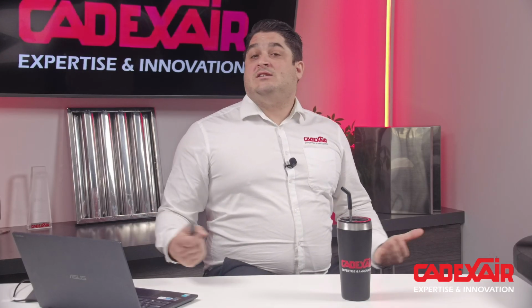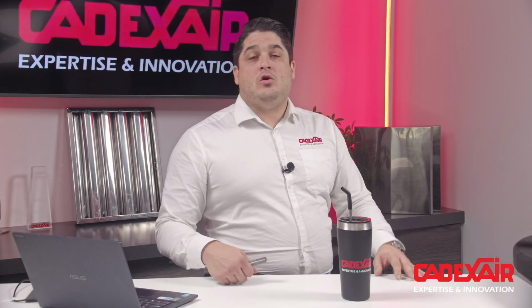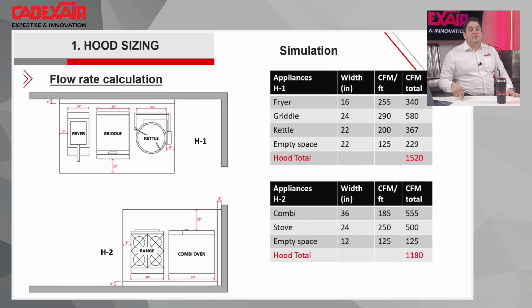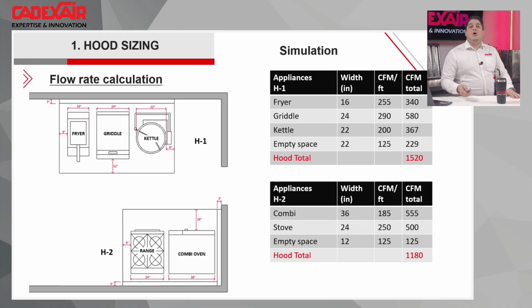How it really happens at Cadexair is, when we are creating the system for each hood, we have drop-down lists with equipment and attributes, and often the real model of the equipment. We choose the equipment with the attributes, and this is linked to a CFM, and we get the exact value of the airflow. I will not do the math right here, but we know the length of the hood and the length of every cooking appliance, so we take all the gap. In that case it's 22 inches of gap, so we will add 229 CFM. Sometimes we are stuck, and we can reduce this value to fit with other considerations.